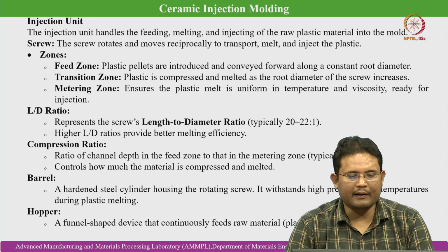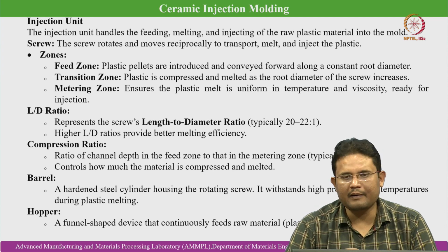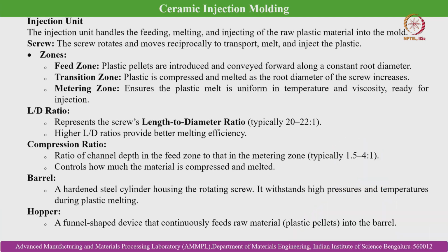Okay. So there are different segments, like we have discussed the process, and if we talk about the important takeaways, like the injection unit: the injection unit handles the feeding, melting and injecting of the raw plastic material or polymer-metal or polymer-ceramic mixture into the mold. And the screw is relevant in case of screw based machines.